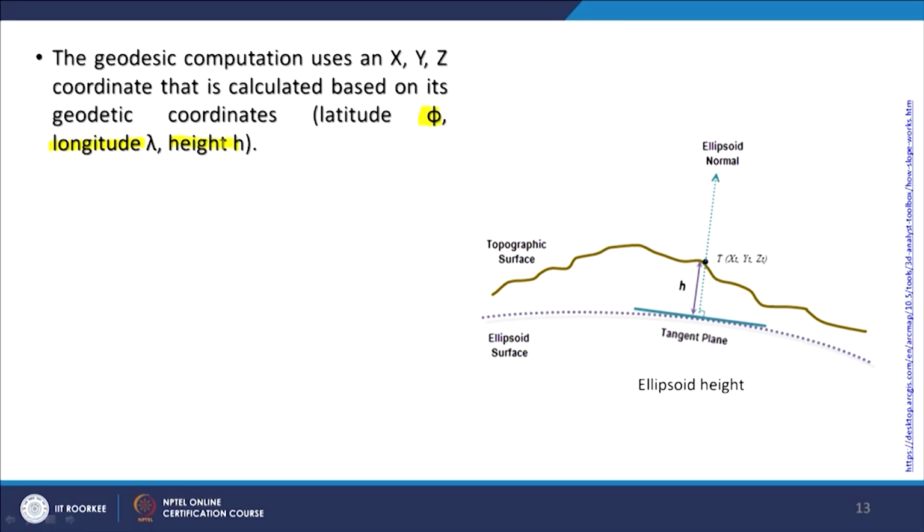Now, as I have mentioned, more complications will come once you go for more accurate estimations of slopes. I am still using the word estimation because after all a digital elevation model is a model; it is not a true one-to-one scale thing. The real one is on the ground only.